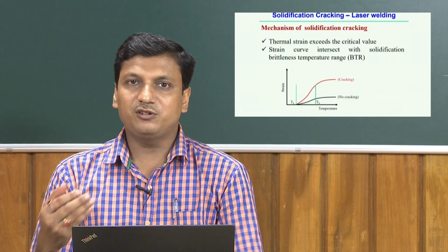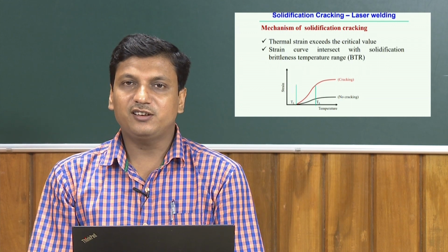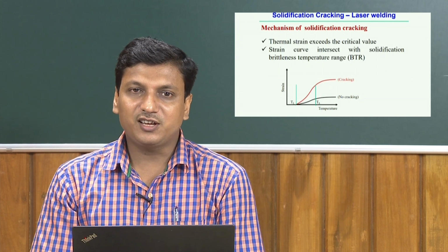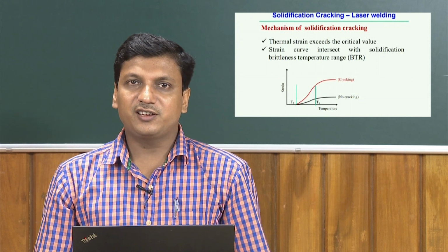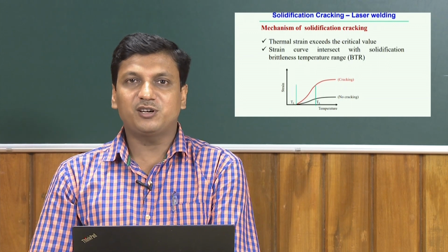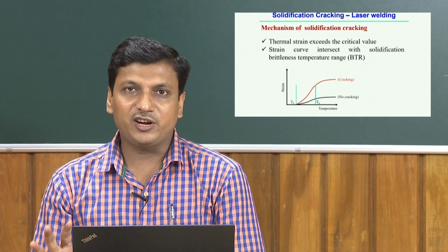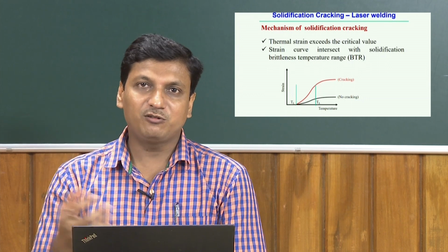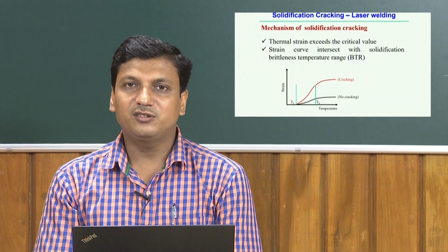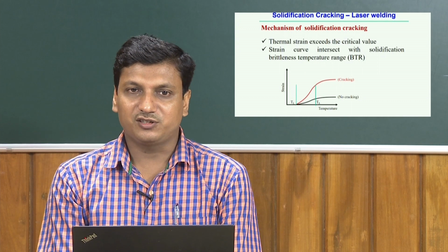If we look into the mechanism of solidification cracking, which is very specific to the laser welding process, and link temperature and strain, when the thermal strain exceeds the critical amount of strain, that strain induces cracking during solidification in the laser welding process.